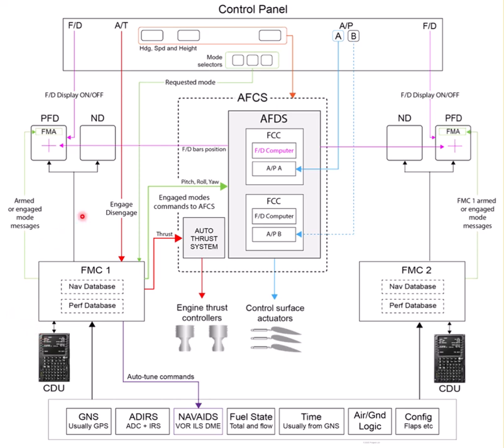Remember that using the EFIS controllers, you can ask the ND to show the altitude for your next waypoints on the screen. Okay, so by pressing the data button on the EFIS controllers, you can actually see more information on the navigation display. So that might save you having to go into the CDU to do that. So I hope that's helped.